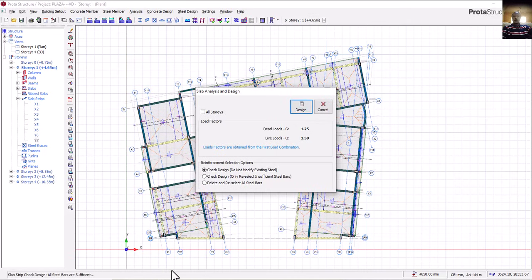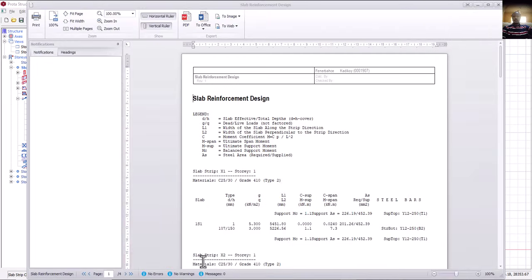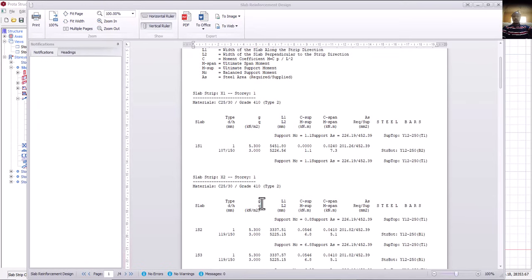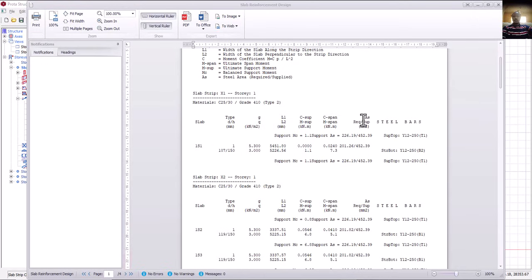So merely looking at this, you know that your reinforcement is perfectly okay. Just like when we are calculating manually, whatever we have calculated, we go to our chart and pick. We are not expected to pick any value less than the area calculated, because this area required is the area calculated, while the area supply is what we have gotten, your choice of reinforcement from your chart. So automatically this one is very, very okay.